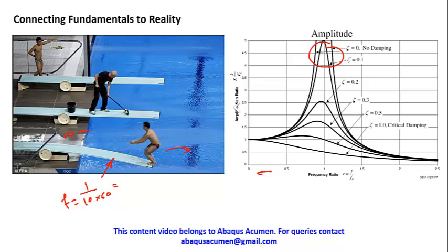And somebody comes and jumps very frequently. So one comes, jumps very fast, or this guy dances on this, starts putting some movement, then your loading frequency is higher than the natural frequency. You are in this region. So your response is much lower than the static response.